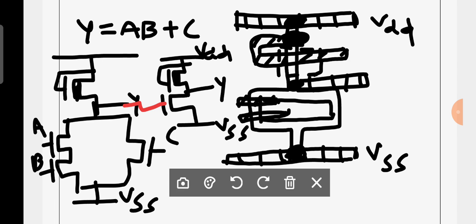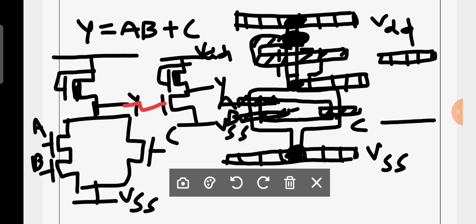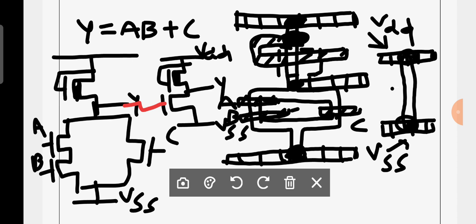This is polysilicon. This is, let us consider, A B, and this is one more transistor C, and you have to draw an inverter here. Therefore you should take a metal like this, and you should take a metal like this. It becomes VSS, it becomes VDD, and you should take a diffusion in this fashion. Are you clear? And you should consider a depletion mode transistor.